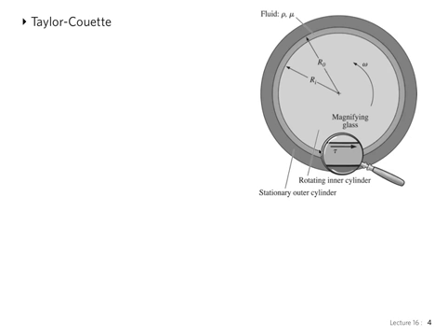And in this case, the solution that we just derived is in fact a good representation of what's happening between the two cylinders. Of course, you can think immediately of the applications in terms of lubrication theory, right? This is the typical situation that you may have. A very narrow gap, for example, well, they're not rotating, but if you think about the cylinders in an internal combustion engine, you also have a very narrow gap that's filled by oil, right? A lubricating fluid. In that case, it doesn't rotate.